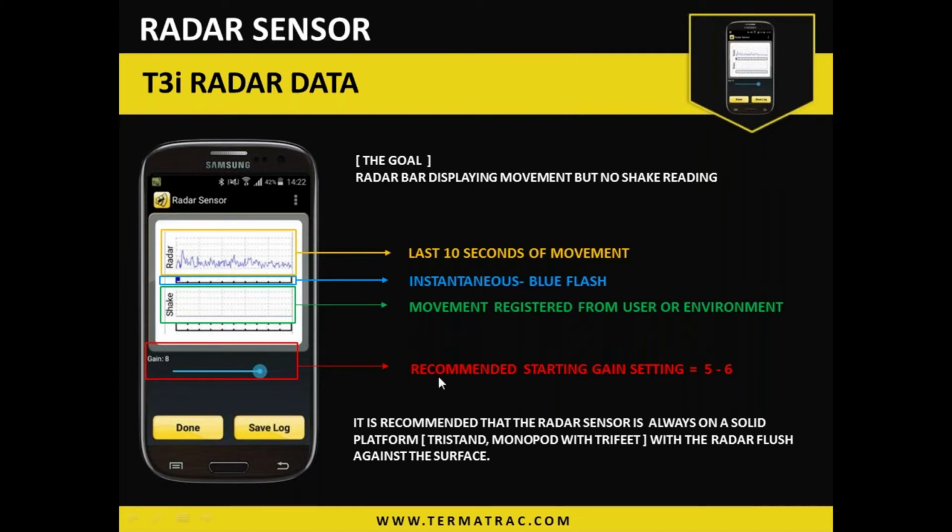As we go up in the gain level, it does become more sensitive to movement, excess movement of the device itself. What we have found, anything above gain level 8 can be problematic when trying to hold it with your hands. So utilizing other tools or equipment to keep that unit steady where it needs to be, is what we have to do there.